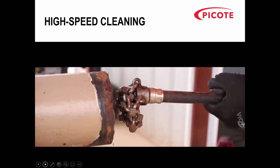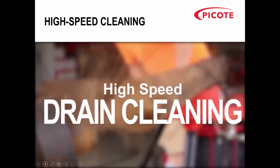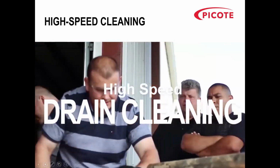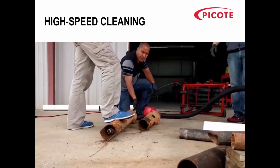So this has got what we call the cyclone chain on there. It's fixed for the diameter of pipe, and you can see how much dust is coming off. Each machine has a remote control foot switch, so you can use both hands. And it just rotates around. So the speed that they go at, it shreds tree roots, it turns scale and encrustation into dust. And they are very powerful, but very simple and easy to use machines.